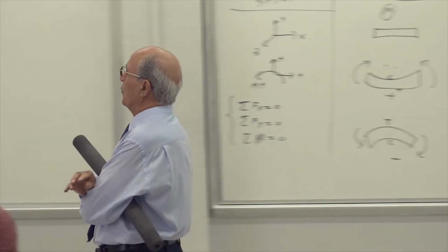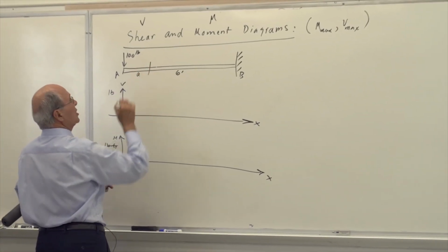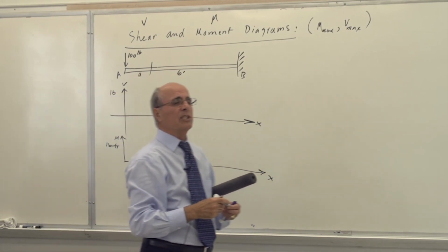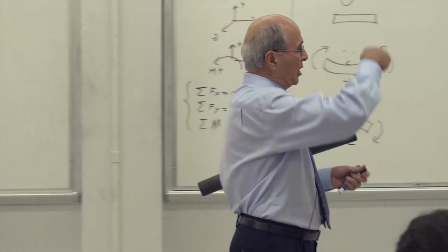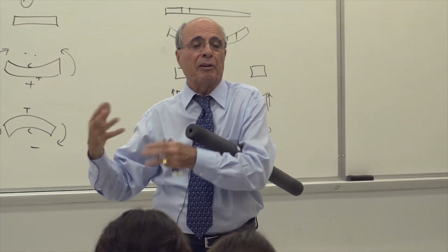Here, anyhow, how do you think the shear is going to be? Let's assume you are at a distance A in your head. This is what you should do. Make a little cut there. What's the shear value? Is it plus or minus? Is it 100? Just do the statics in your head. This does not require a free body diagram.